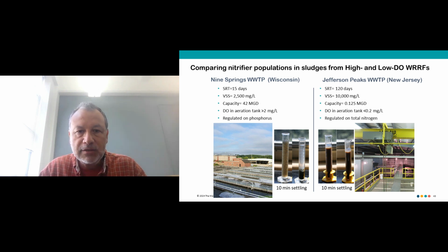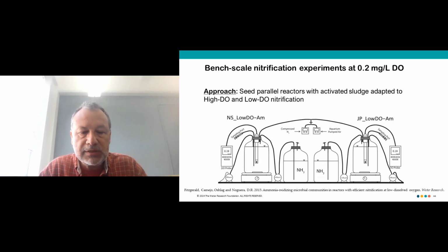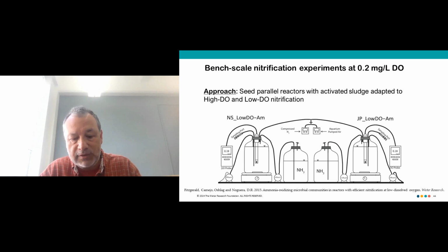So very high concentration of solids, but they were operating already with very low DO for several years when we started this interaction. This was Colin Fitzgerald's master's thesis. We decided to take samples, put them in lab scale reactors at very low oxygen, 0.2 milligrams per liter in each case, and observe over time what would happen. Would they start nitrifying? Would they not nitrify?